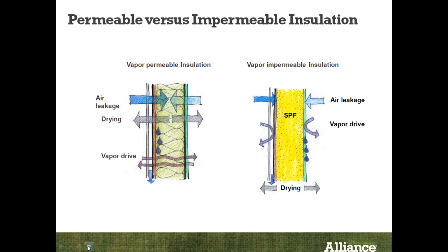So lastly, if I look over the last 70, 80 years, I know Owens Corning brought in their fiberglass bat in 1938, which is a vapor permeable product and a very good insulator. Some of the downfalls with vapor permeable insulation is that it creates a little more potential and risk when we talk about condensation in higher performing wall assemblies. Vapor permeable insulation allows air leakage to occur if there's no vapor barrier or air or vapor retarder behind the drywall, and allows for potentially cooling off condensing planes.